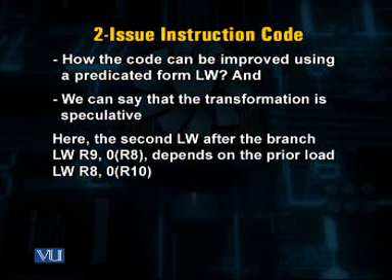Here, the second load instruction after the branch instruction, that is, load R9 from the offset given by the contents of R8, depends on the prior load, that is, the load into R8 from the offset given by the contents of R10.